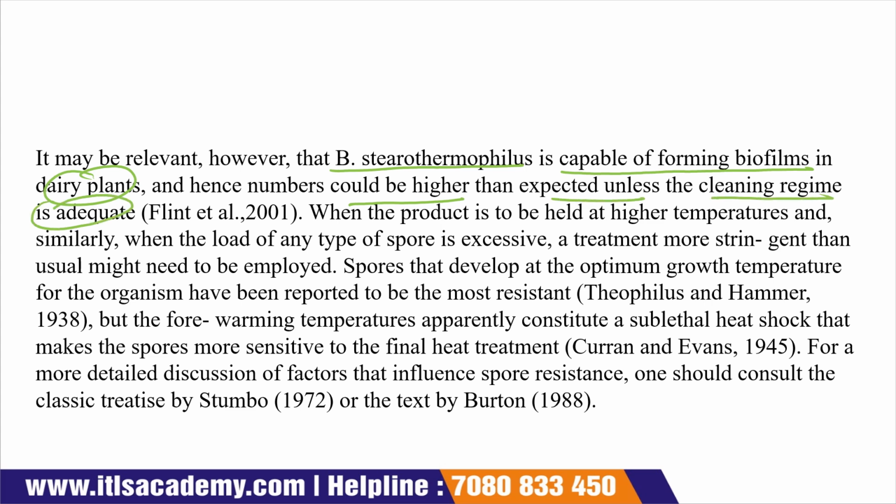If there is not proper cleaning, then there is a higher chance that Bacillus stearothermophilus can grow, forming biofilms in dairy plants. When the product is to be held at a higher temperature, and similarly when the load of any type of spore is excessive, a treatment more stringent than the usual might need to be employed.